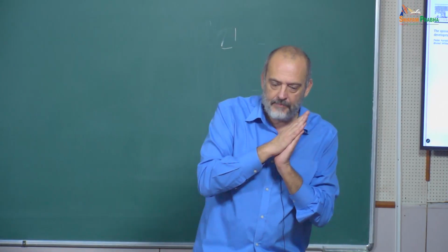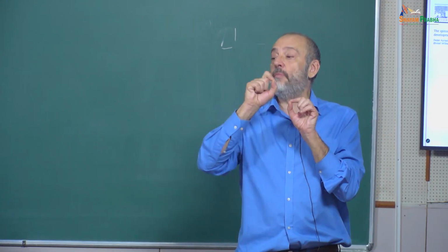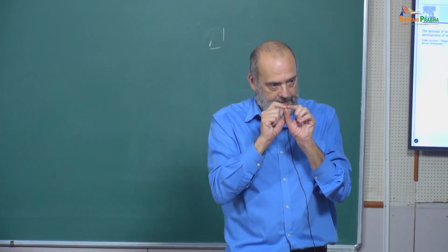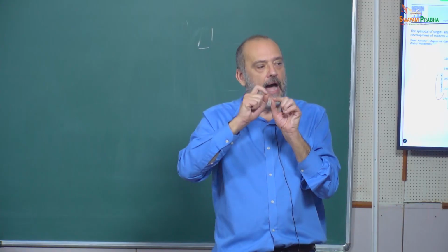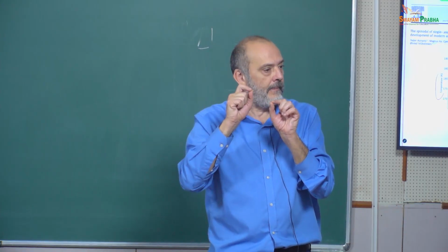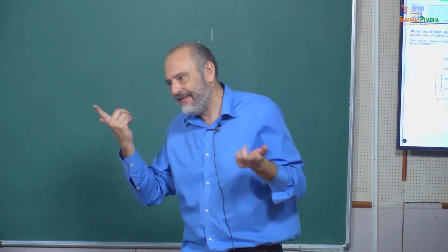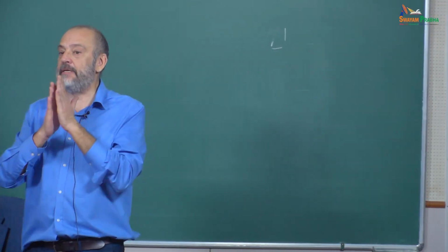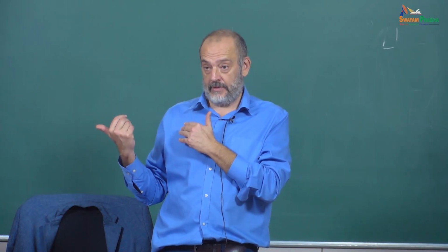And at a given point, we are entering a little bit into the metastable condition. So the probability of nucleation becomes higher and higher. It becomes infinite, let's say probability 1, when we are going to the spinodal. So this means that it's not possible to overcome, because we are going to nucleate and have the other phase. Okay?